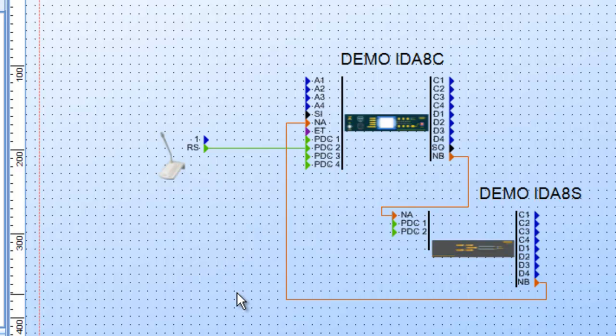All right, now when you first plug in and wire a PPM-AS microphone station, you plug it into the included junction box. The field wiring goes from the IDA8C's PDC console ports with a standard 4-pair Cat5e or Cat6 cabling to the junction box. The actual PPM-AS is a 5-pair shielded, about a 2-meter long patch cable that plugs into the junction box.